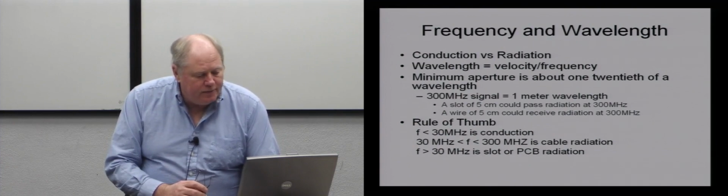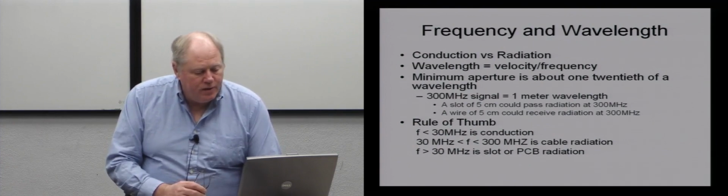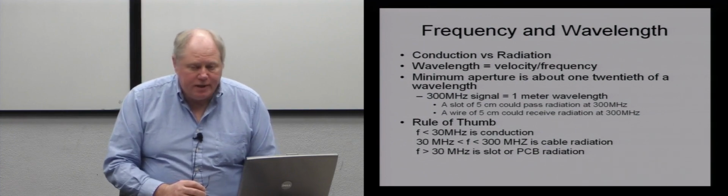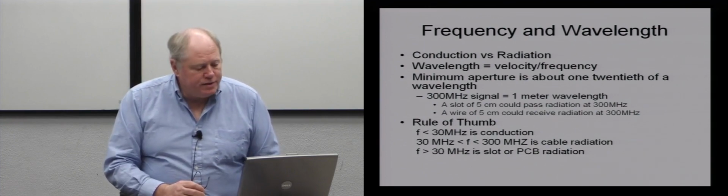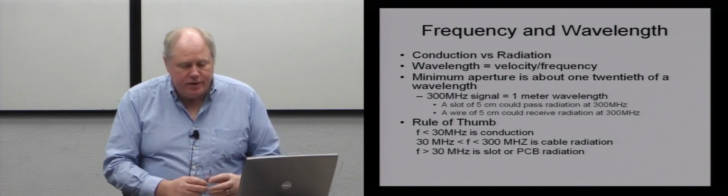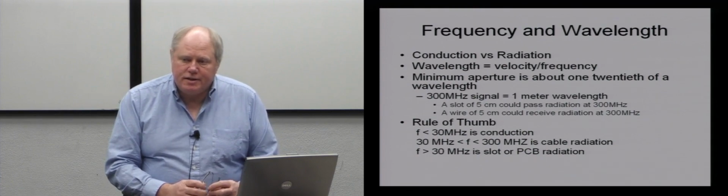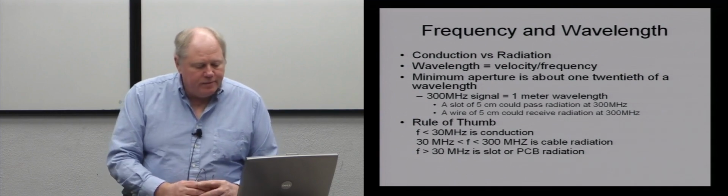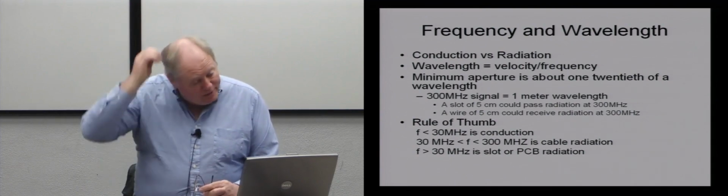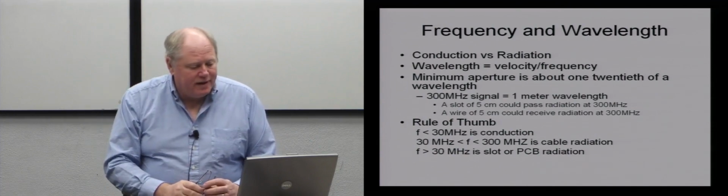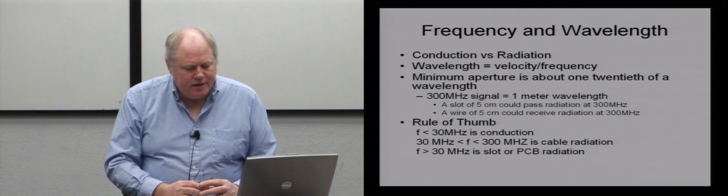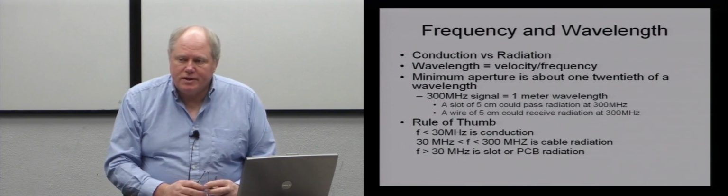And if you're trying to keep high frequency signals in, you have to have it in a metal box that has holes and slots or whatever it is. I mean, you can't just put everything in a metal box, because you need to get things in and out. You need to get signals in and out if you're going to use it for something, unless everybody's just going to live in there, and it might not be a very popular product. So you have to keep that in mind, and if you're talking about now a 3 gigahertz signal, things become 5 millimeters. Those are really tiny dimensions.